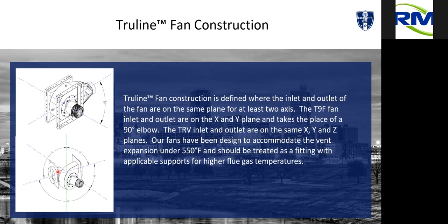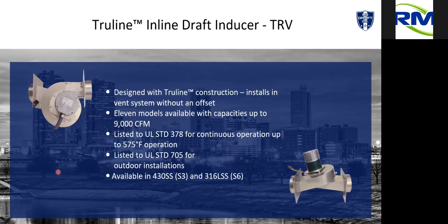And they were able to hang all 6 of the inline fans within a day and a half. Now, they still had some electrical and finish work, but basically all they did was take out a piece of pipe, a couple of adapters with adjustables, and pop the fan into place. They didn't have to rehang anything downstream from that. So it was a great retrofit fan to fix a problem on the fly rather than having to repipe everything, which is kind of why it looks the way it does. It's a little quirky here in the middle. That's to make sure that the inlet and the outlet are basically straight through.